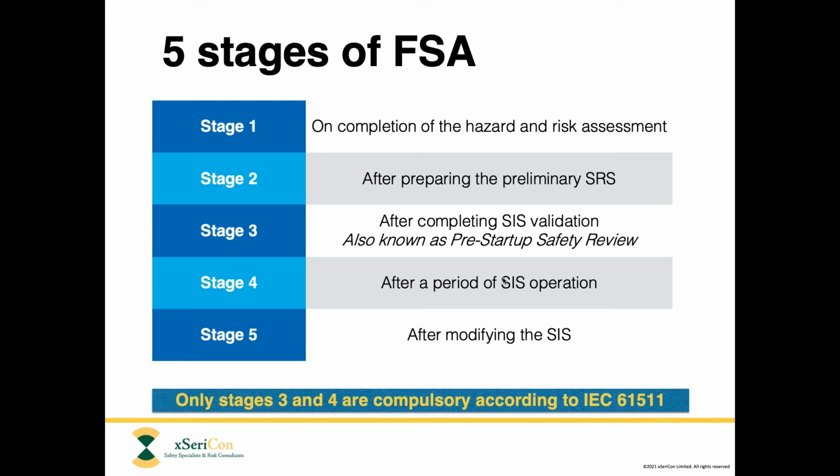Now, according to IEC 61511, all of these stages are recommended, but only stages 3 and 4 are actually compulsory. However, we do strongly recommend that you perform the FSA at all of these stages, because, again, bearing in mind that the purpose of it is to minimize the chances of human errors leading to systematic failures that could eventually result in a very serious accident.